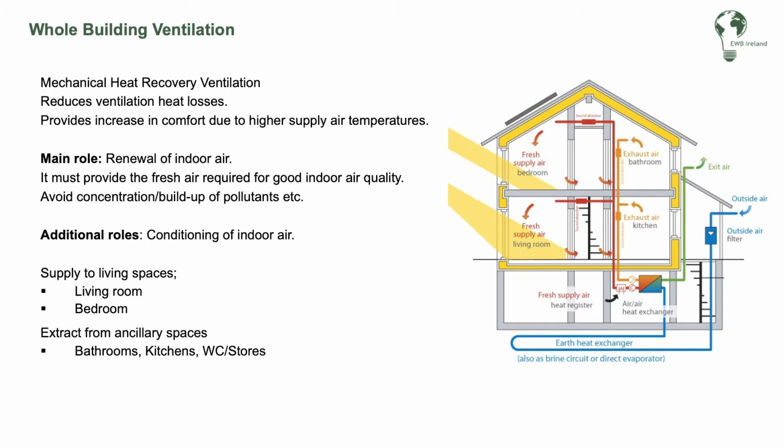Getting into this part of it, a lot of buildings are going this route. The driver behind this is because, with the likes of NZ passive house design, buildings are getting so airtight. The driver for this is to provide good indoor air quality and air change rates. And the simple concept behind it, there's a certain amount of pollutants, depending on your building materials. Some building materials have VOCs in them. Things like formaldehyde, they can build up in it. Not so much anymore, but it used to be an issue.